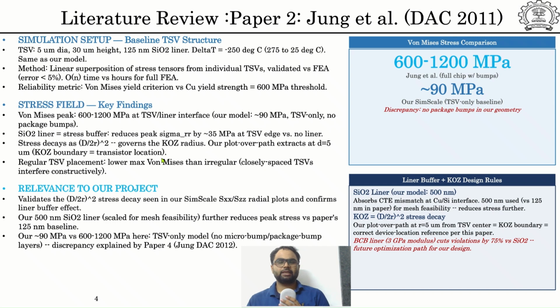Coming to the key findings of the paper, stress is highest at the TSV liner interface. It ranges around 600 to 1200 megapascal. The SiO2 liner acts as a buffer and reduces stress. Stress decreases with distance, inversely proportional to the square of the distance. Regular TSV placement results in lower stress and irregular placement results in higher stress.